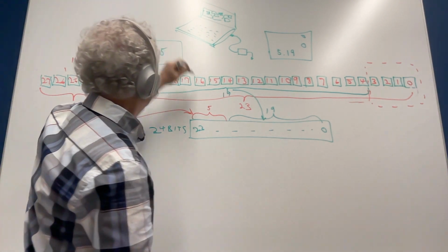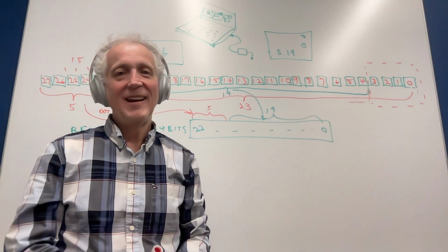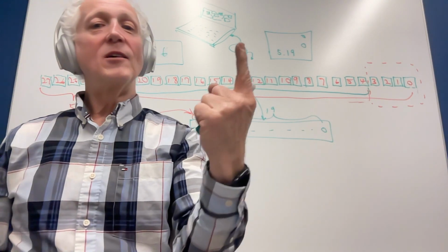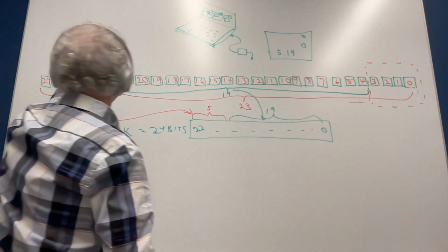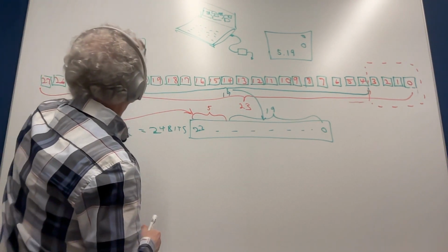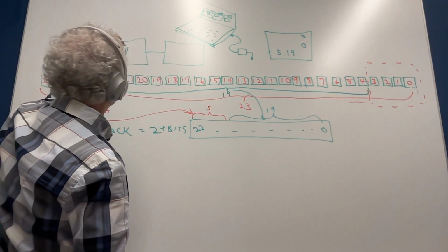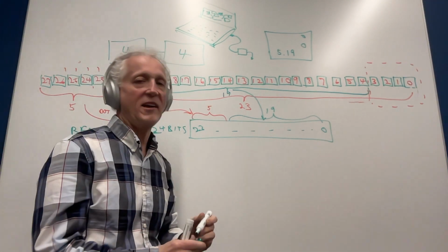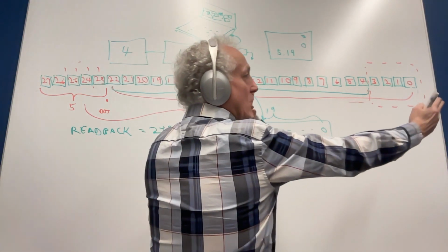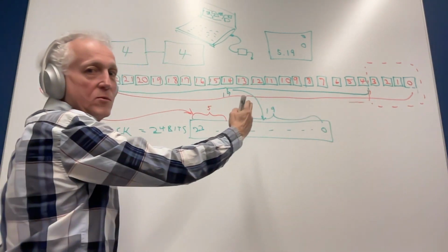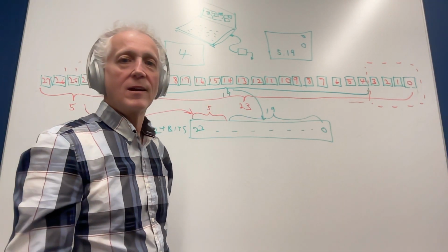I can't put a 16 in there. It won't take a 16. So we can't multiply by 16 directly with one block. So what we do is you take 2 multiply blocks, you hook them up in series, and you multiply by 4 twice. Then you get to multiply by 16. So we shift over 2 bits, and then we shift over 2 more bits, and we got it. Then we do the read back, and we're good.